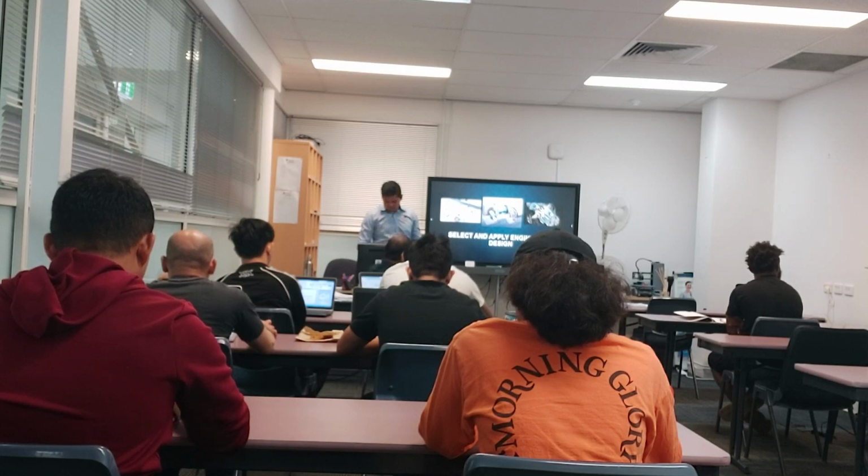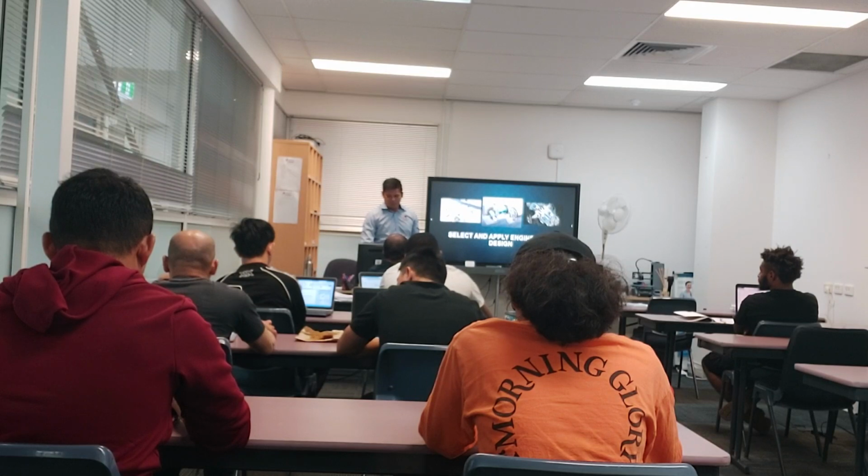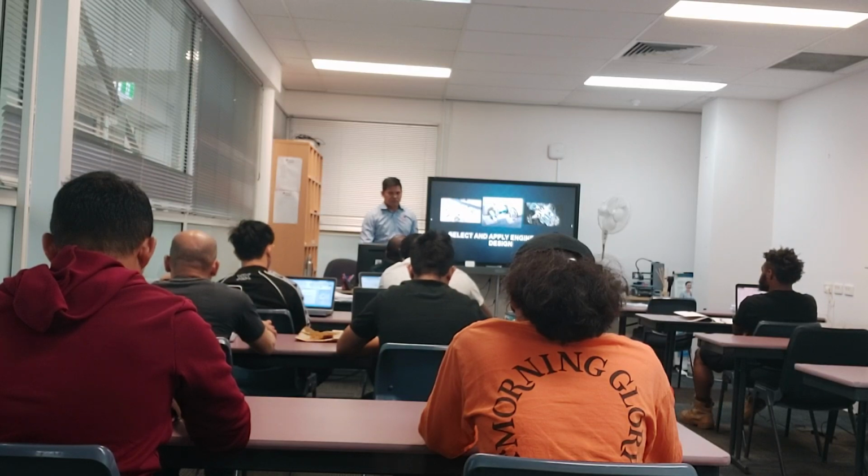Once you do the calculations of the design, you come up with the gear diameters and the number of teeth where the gears are meshing each other. Based on the number of teeth, you optimize the combination, the ratios, and you manufacture the gears. Based on the application and the amount of power generated by the gearbox, you decide on the material of construction of the gears.